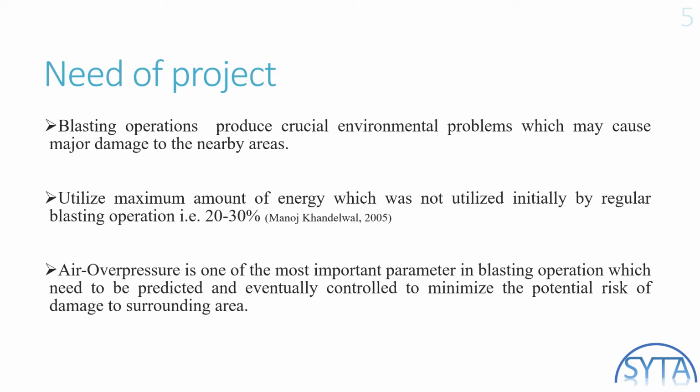Need of project. Blasting operation produces very crucial environmental problems which also cause major damage to the nearby areas. According to Manoj Khandelwal in 2005, only 20 to 30% of blasting energy is utilized for rock fragmentation or to break the rock, and the other energy spreads into air blast or air overpressure, and ground vibration.